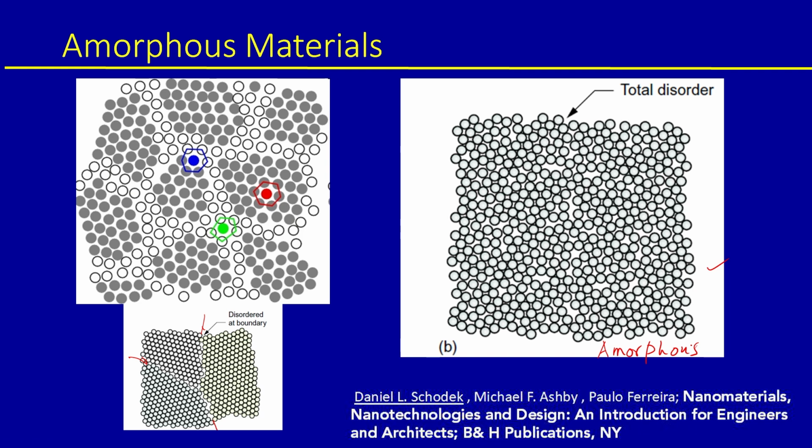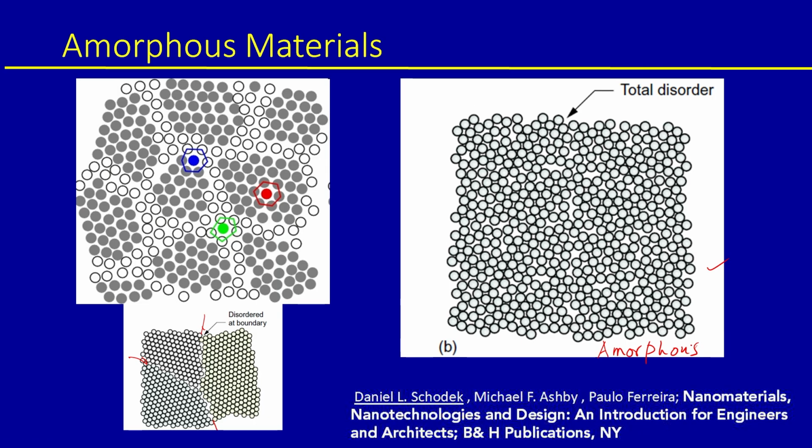Since atoms are not in ordered arrangements, what will you actually see? Properties will change definitely. Here atoms are ordered nicely except at the grain boundaries, but here atoms are ordered haphazardly, there are no grain boundaries here. Since there are no boundaries, light does not scatter, because light can easily pass through the glasses. This is the main reason. There are many other reasons, but this is one of the main ones. So, light can easily transmit through the glasses without much bending, and that is why you use glasses. Remember this. Glasses are very important, even my specs has a glass, right.